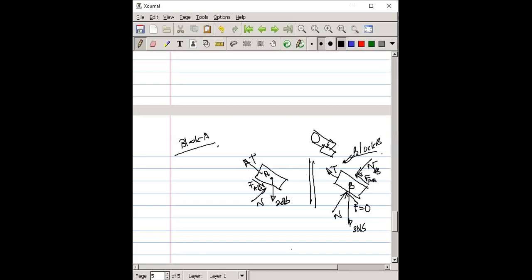Why? Because see, this is the resultant. One force will come here: one tension, one normal, and one its own weight. So 4 forces. After converting into the resultant force, we still have 4 forces in a system applied on a block, right? So for that reason, we cannot apply Lami's theorem here. So what do we have to apply? Simply find out summation of Fx is equal to 0 and summation of Fy is equal to 0.